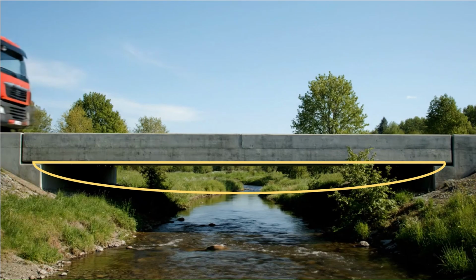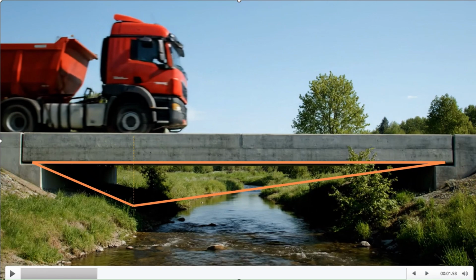First of all, we'll use first principles to calculate the bending moment from a uniformly distributed load, such as the deck self-weight. Then we'll look at the bending moment from a point load applied at any point in the span. And then we'll look at the combined uniform load and point load, and we'll show you how to work out where the maximum moment occurs, and then we'll look how to calculate that moment.